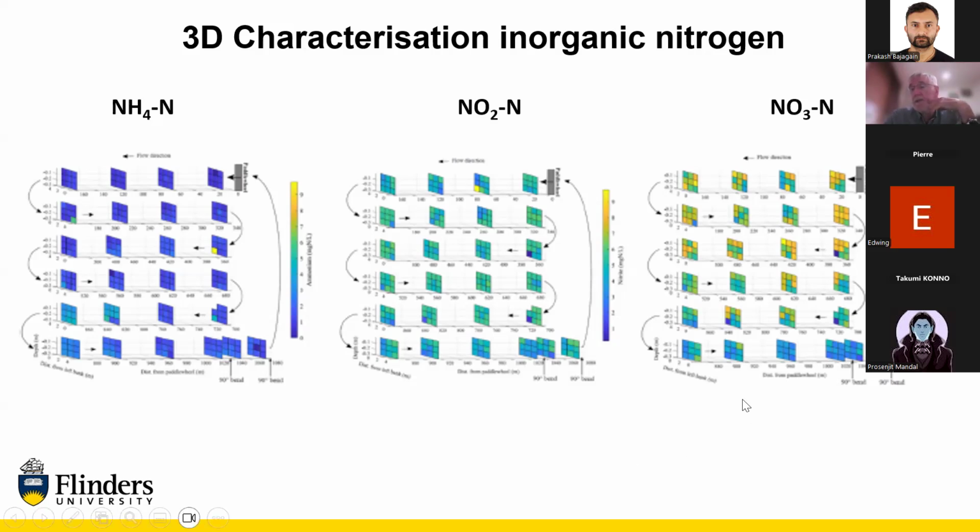We don't understand why we've got high rates of nitrification through the pond generally, and in this last channel here, we're seeing lower concentrations of nitrate at this point. We could have a reaction where the nitrate is being denitrified. That is, in reducing environments that might be in the center of the aggregates. The reducing environment means that the nitrate is reduced to nitrogen gas and leaves the pond as nitrogen gas.